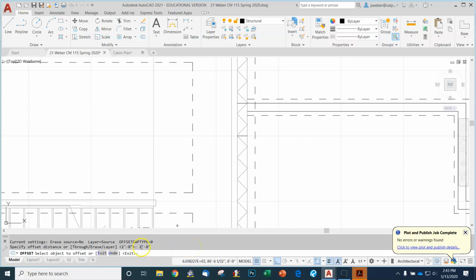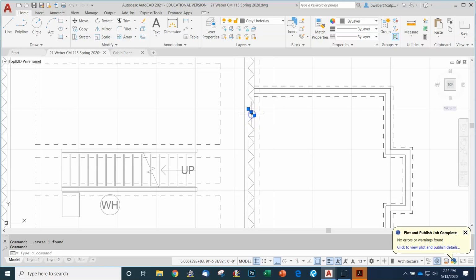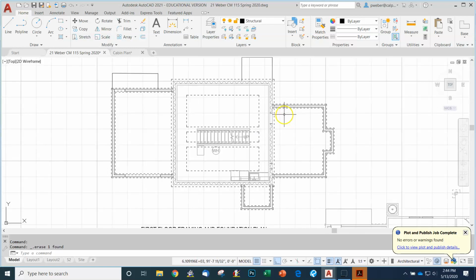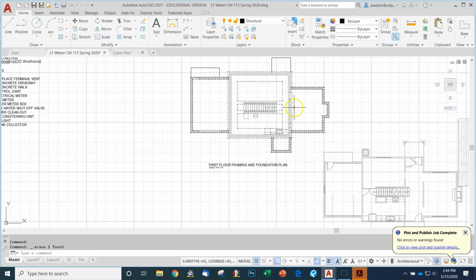In Revit, if you put 2 space 8, it would see it as 2 foot, 8 inches. In AutoCAD, you have to put in 2 feet space dash 8 inches. Then it says select the object, you click here and you click down. Perfect. Good. I press escape and I'll delete this line here, my original line. Something else I could do too, would be good to see, is go ahead and delete this hatch that Revit gives you. Oh yeah, good. Good, because that's a hole there.